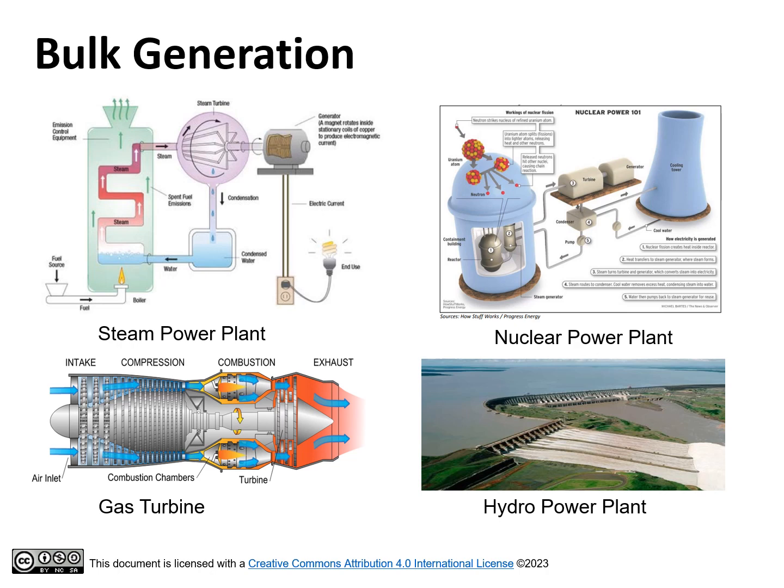Generation power plants are the most important components in the electrical power grid. Bulk generation mainly uses thermal or hydropower generation power plants. Thermal power plants convert thermal energy into mechanical energy using different types of steam and gas turbines to convert mechanical energy into electrical energy.